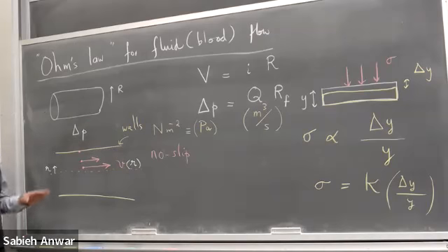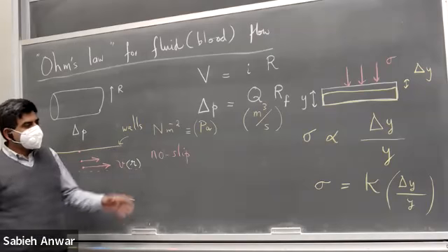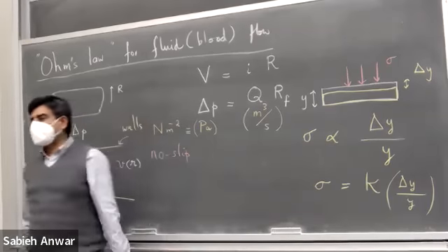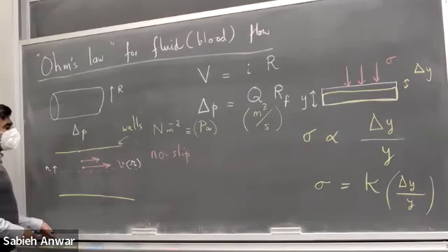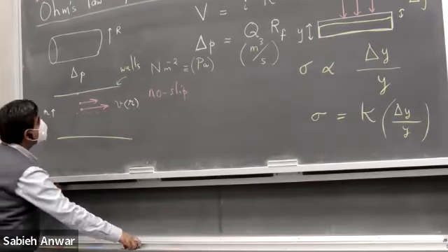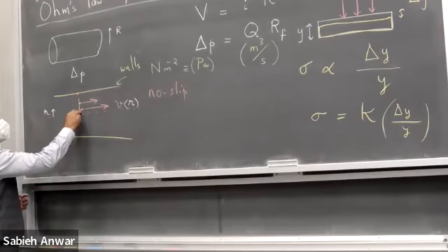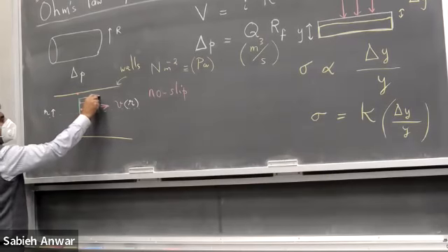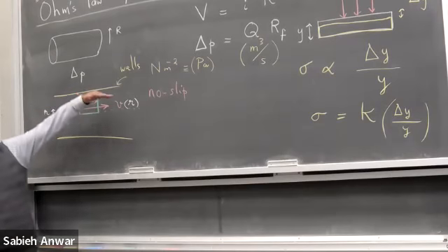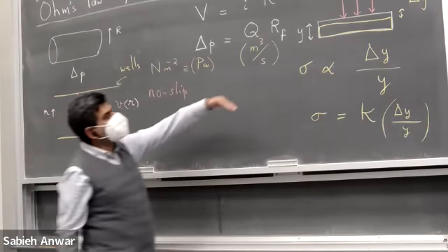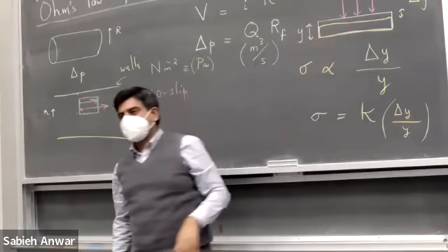Now, what we would like to do is come up with a relationship similar to what we have for the stress strain relationship in solids. If you observe carefully, and if I were to draw a small section here of fluid, there is a force acting on this fluid that is parallel to the surface of this section. Here, the stress was normal to the section.